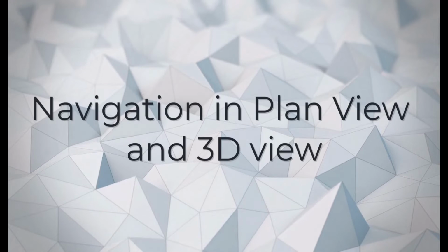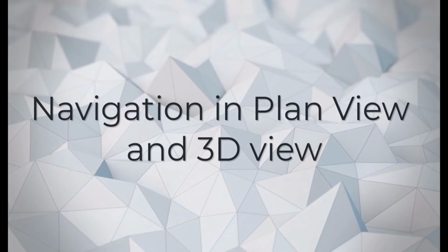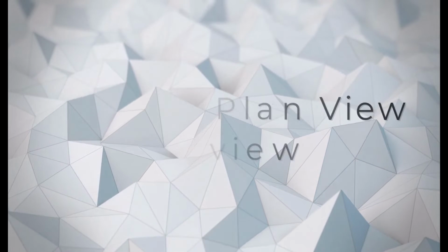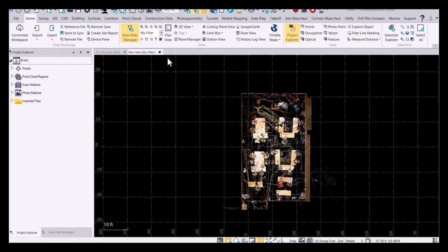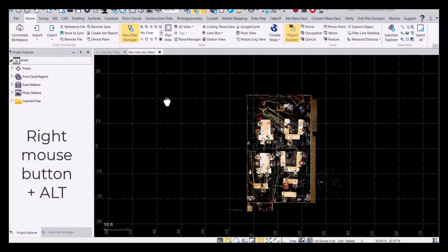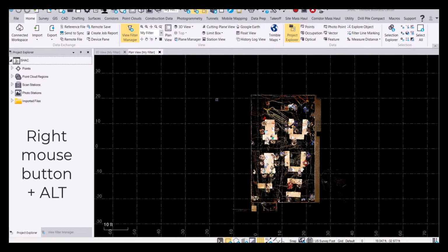In this episode, we're going to look at some different ways to navigate through plan view and 3D view, especially some that you may not know about. So we'll start off in the plan view, which is a 2D view. We already know if you want to pan, you're going to press and drag the right mouse button. If you want to pan at a slower rate, you're going to press Alt and do the same thing.